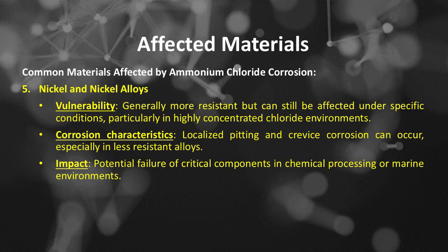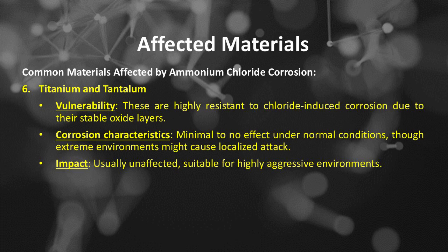marine environments. Number 6 of the common materials affected by ammonium chloride corrosion is titanium and tantalum. The vulnerability of titanium and tantalum: these are highly resistant to chloride-induced corrosion due to their stable oxide layers. The corrosion characteristics on titanium and tantalum: minimal to no effect under normal conditions, though extreme environments might cause localized attack. The impact on titanium and tantalum: usually unaffected, suitable for highly aggressive environments.